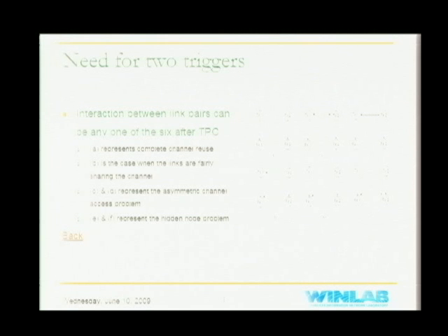Scenario E and F represent typical hidden node problems. In the first case, RX1 is in the transmission range of TX2, and we see frame losses only at RX1. In scenario F, we see frame losses at RX1 and RX2 because of simultaneous transmissions.